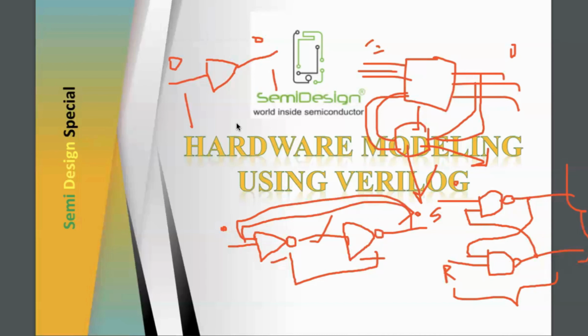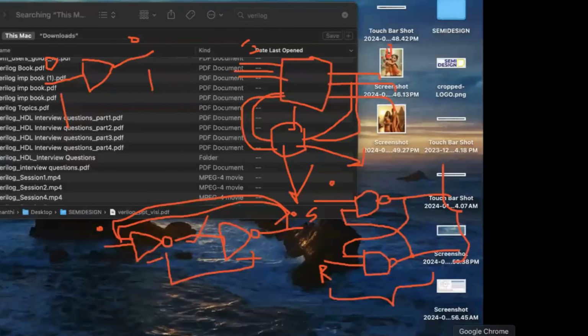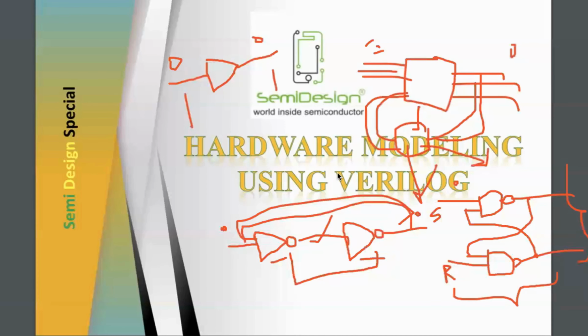What is the drawback of level triggering? It can change the output at any instant of time, which is not a good thing for digital circuits. In latches, we get race-around conditions, right?